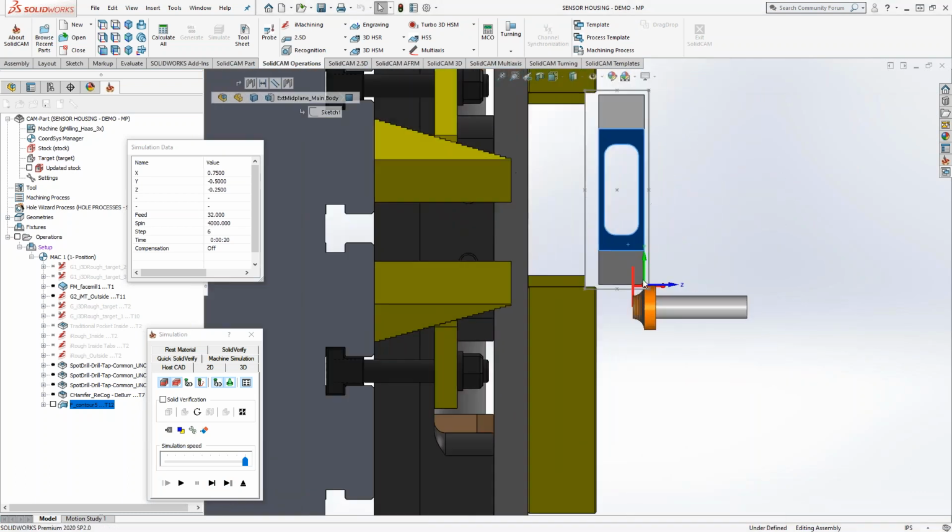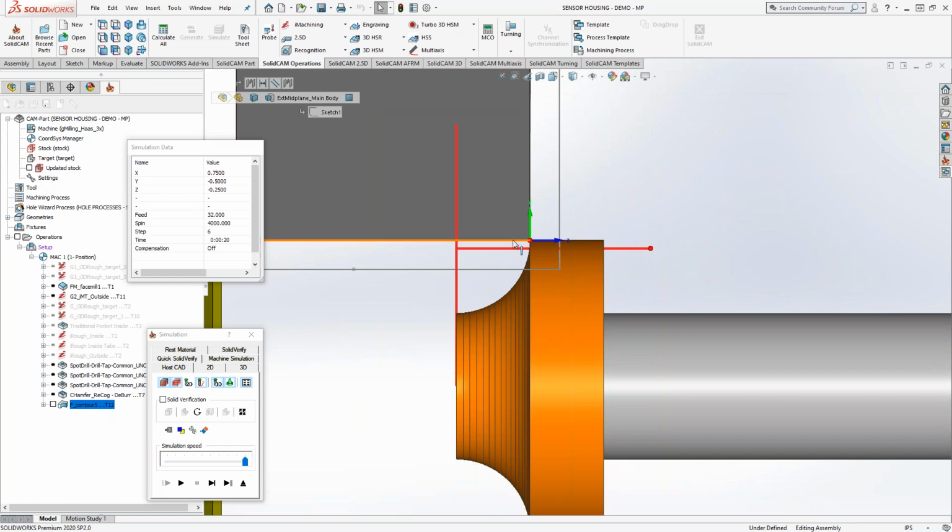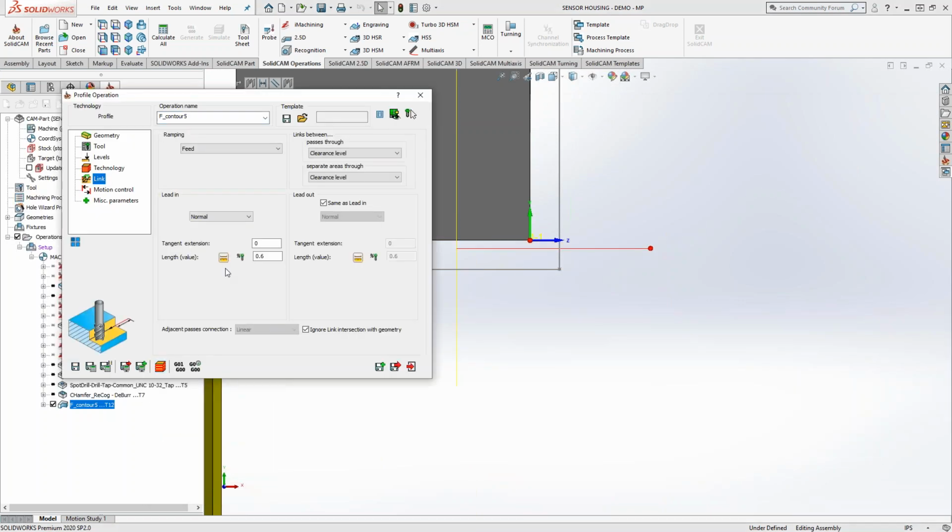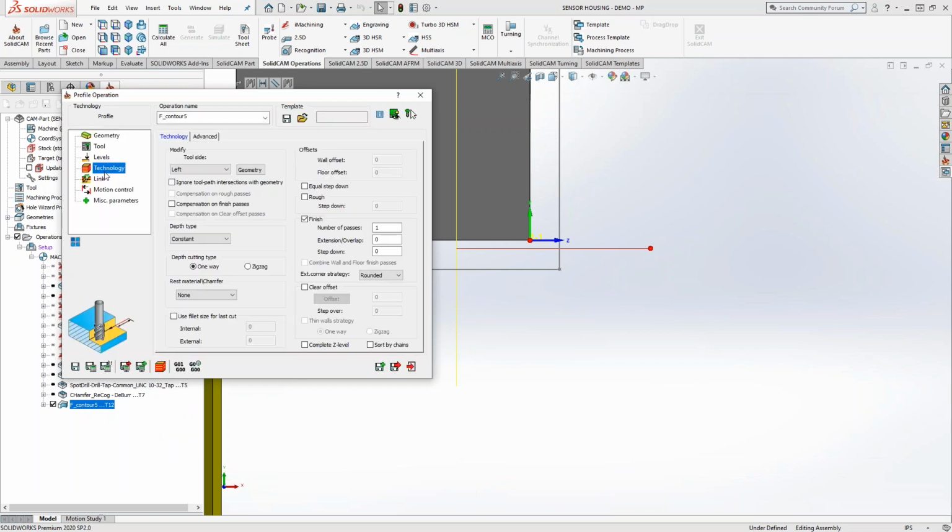So it still thinks that the 1 inch diameter is what is the offset. So I dropped it by that 1/4 inch. I have to bring it in. So to accommodate that, what Mark can do is he can actually, instead of saying that his tool is a 1 inch cutter, tell that tool it is a 1/2 inch, because that's based off of the smallest diameter of that shape.